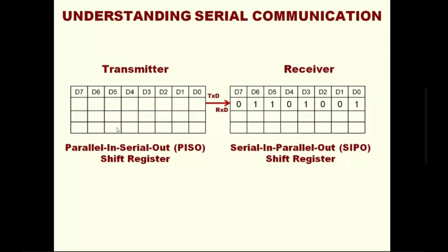The same thing will happen on the receiver side. Before 8 bits have arrived, say for example only 4 bits have reached the receiver, if we copy the data from the serial-in parallel-out shift register unnoticed, we will receive this byte's 4 bits and the previous byte's LSB 4 bits. So we should wait until all the 8 bits are shifted in. How to wait? When all the 8 bits are shifted in, somehow it has to notify. With respect to 8051, it notifies through the RI flag.